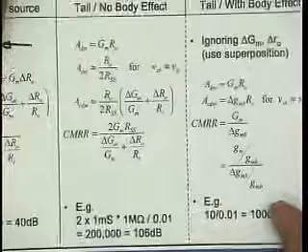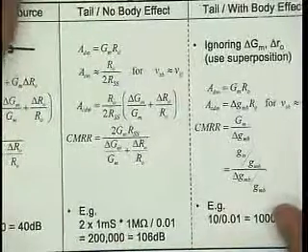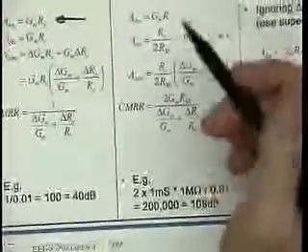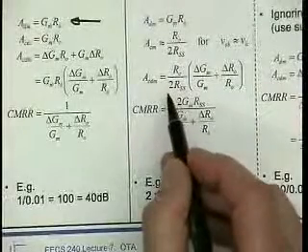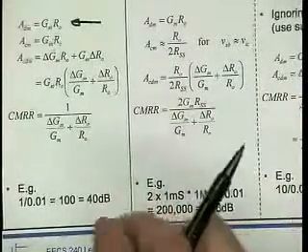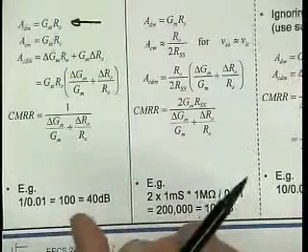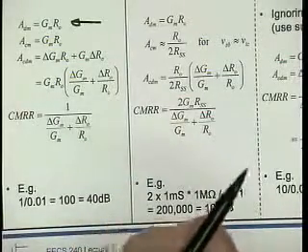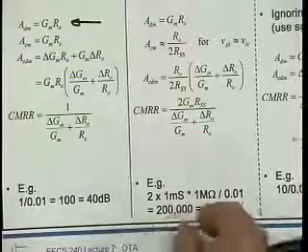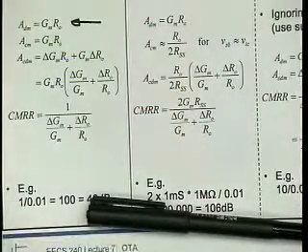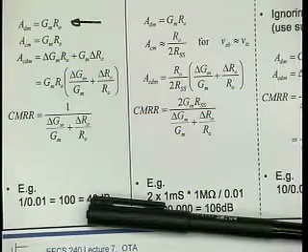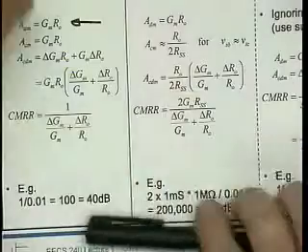So then the tail current source, really what it does is that the current I'm getting now is no longer delta GM times VIC, but it's only the fraction of VIC that actually produces a change in the current flowing into my diff pair.